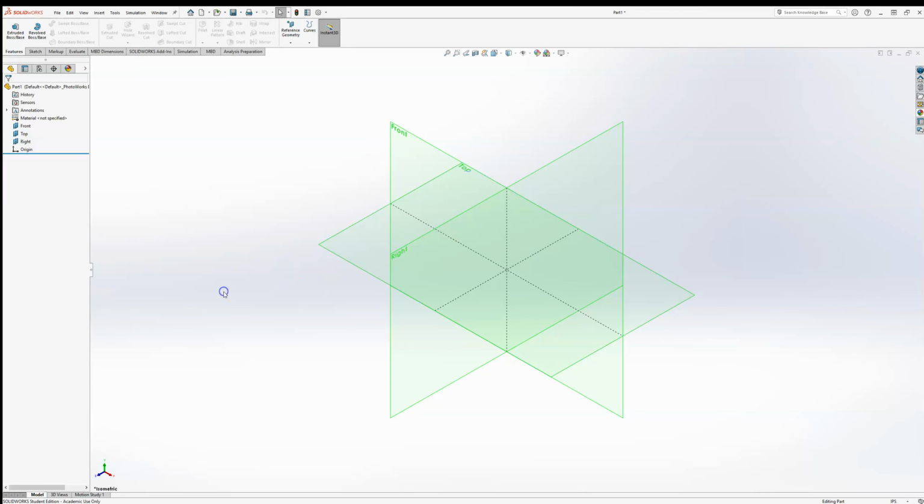And so there are a few different ways to create a sketch. One way, I can just click the plane and I can click that icon right here. And another way is I can come up here. You can see my command manager or my ribbon here. It's got a bunch of different ribbons. Some of them we don't really need, but it does have a sketch ribbon. So I'll click sketch. I'll click create a new two-dimensional sketch. You do have to be careful because there are 2D and 3D sketches inside of SolidWorks. So I'll create a 2D sketch just by clicking right here.